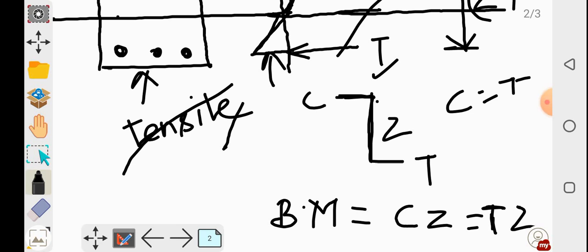So this is the internal bending moment generated due to the material property of this RCC beam section. That means this is the internal reaction which will counterbalance the external bending moment due to external loading. So we have seen how the internal resistance for the bending moment is generated in our RCC beam in case of a singly reinforced beam.